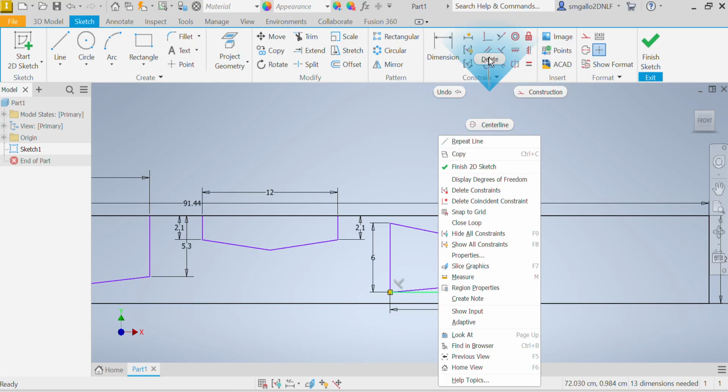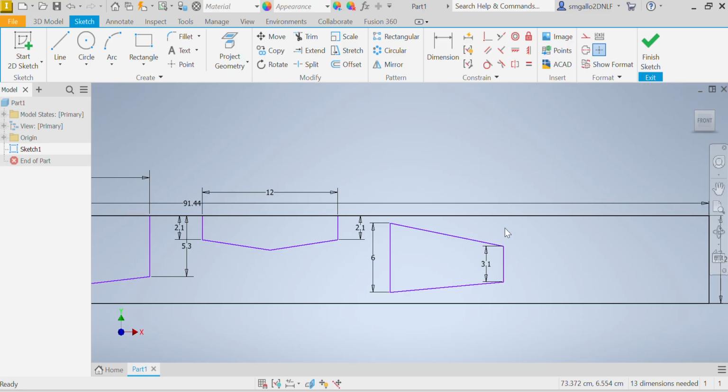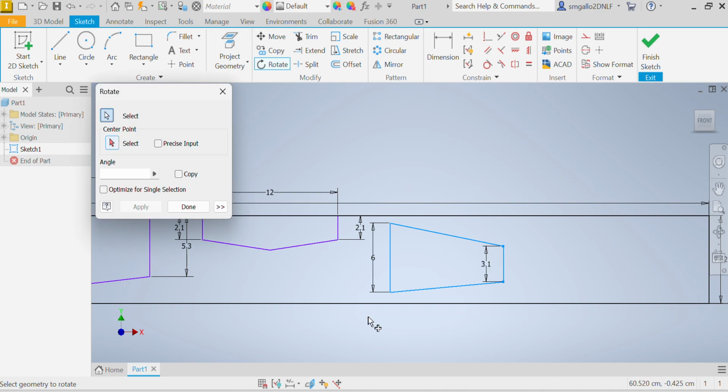And as we are placing our vertical stabilizer onto our grain, we really need to rotate this. This is the leading edge. The leading edge needs to be parallel to the grain. So I have to turn it to be parallel to this line right here. I am going to use my select tool and grab all of these lines together. And I will go ahead and rotate them.